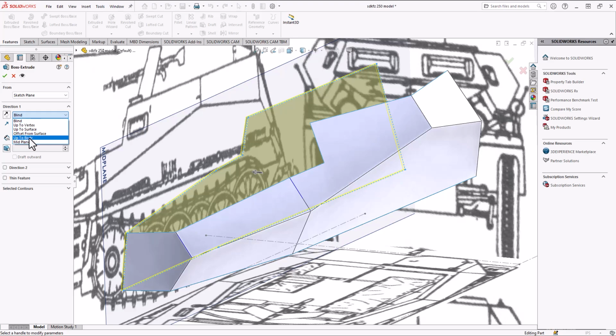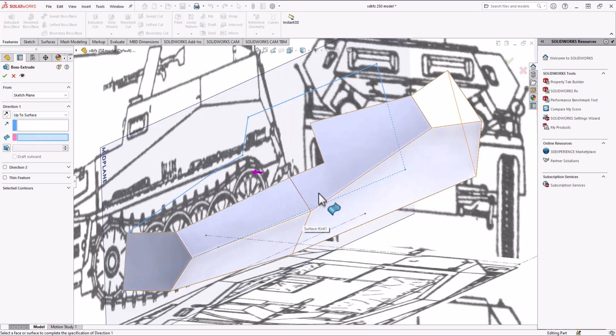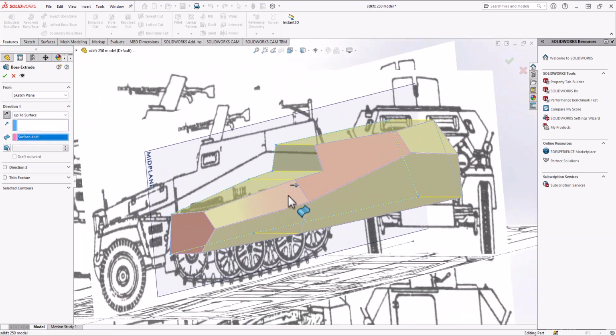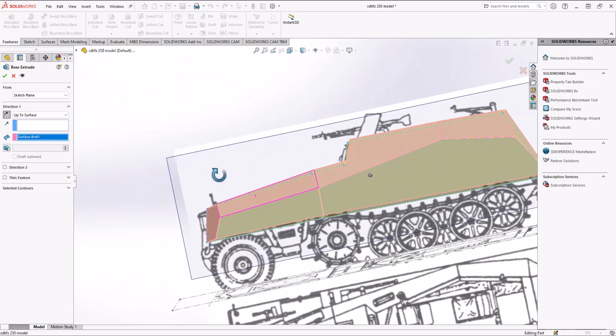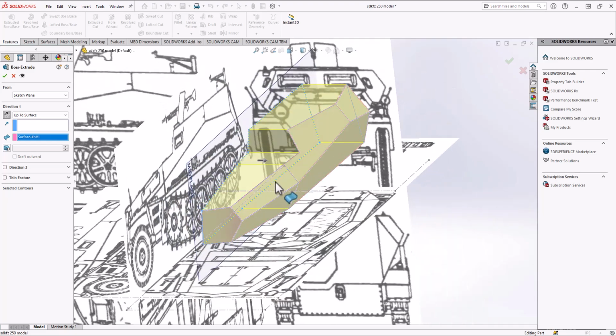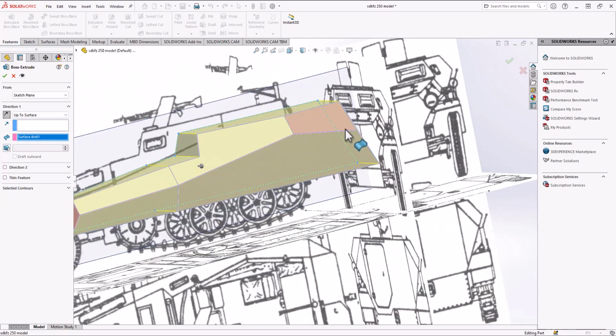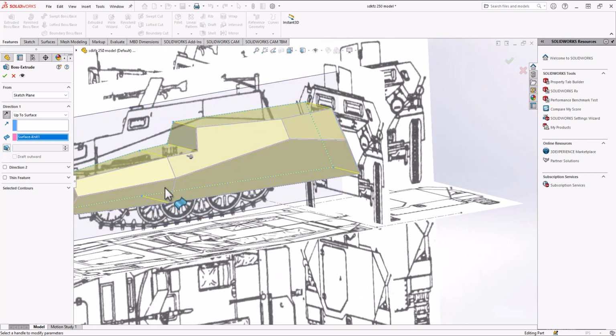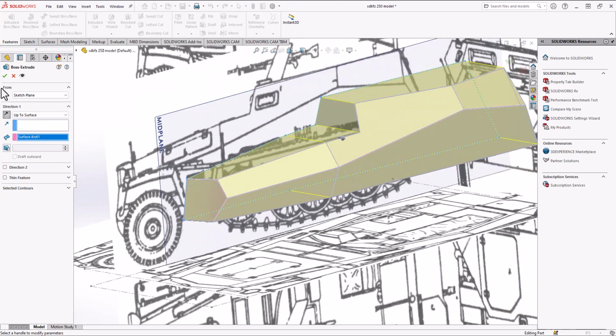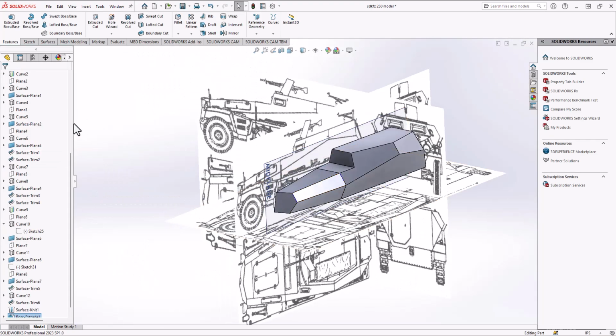and I can go up to surface. And since this is one surface, I can just click on it, and it will just fill it out up to that surface. So there's a few contingencies. The surface has to be basically not intersecting on that extrusion plane, right? So if I had another face or something coming in here, it would have trouble deciding where to go on that surface. But what I can do is I can just extrude there, and now I have this.